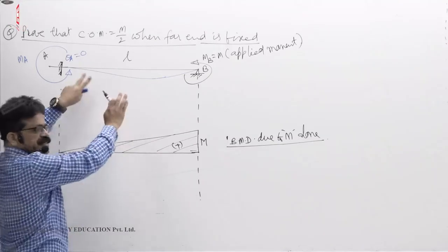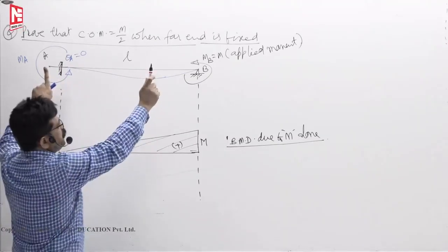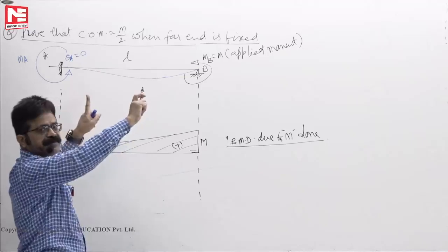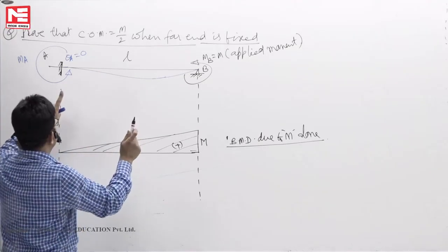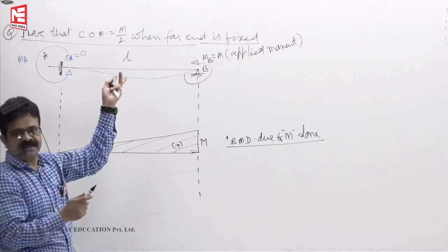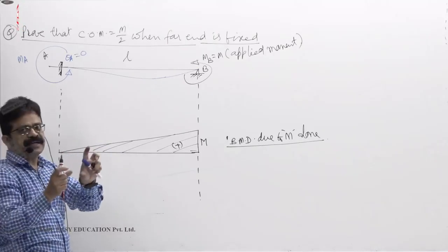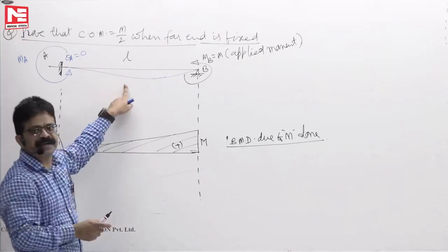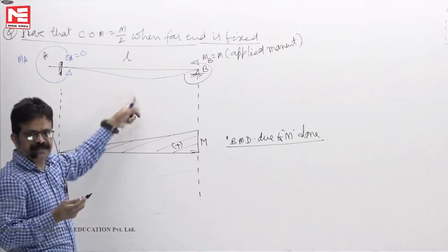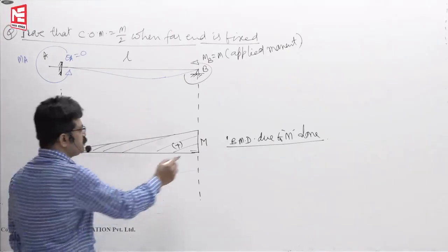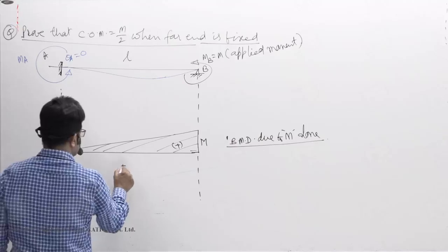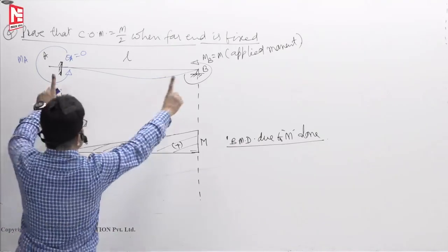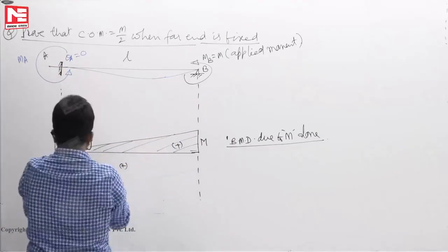This beam is similar to a simply supported beam subjected to a moment M and a simply supported beam subjected to a moment MA. If both bend moment diagrams you add them, you will get a propped cantilever bend moment diagram. Principle of superposition. So due to M alone plus now simply supported beam subjected to hogging moment.